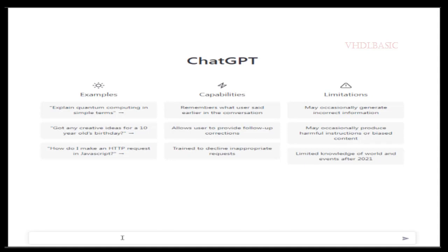Today we are going to see serial to parallel conversion in Verilog HDL. For that, we need to know what a shift register is. A shift register is used to store and shift digital data. It is composed of a series of flip-flops connected in such a way that the output of the first flip-flop is assigned to the input of the next flip-flop. The data will be shifted through the register by applying the clock to the flip-flops.